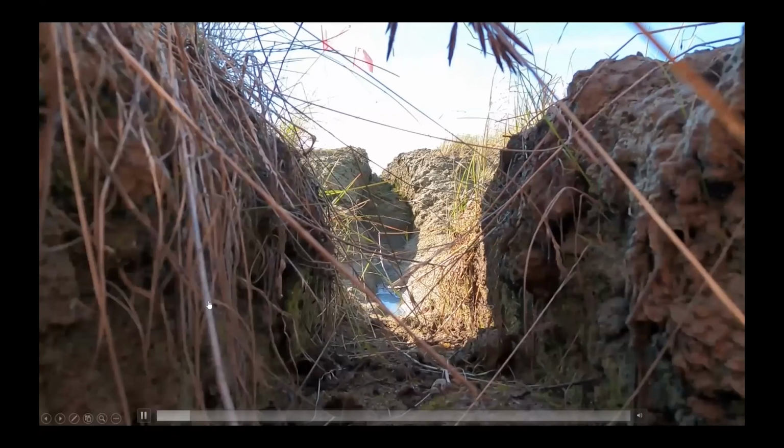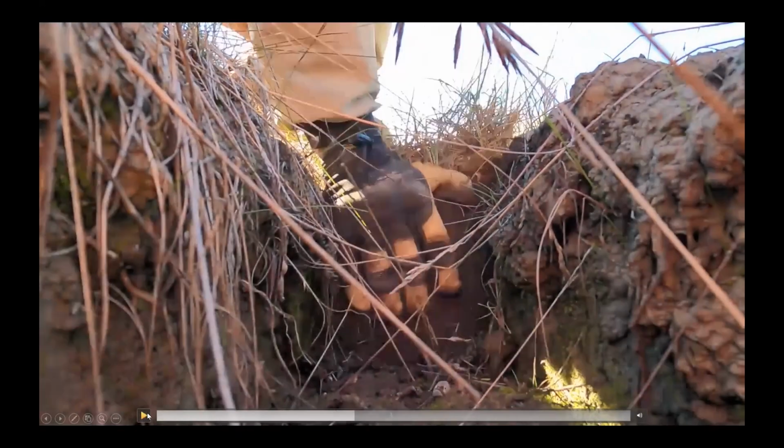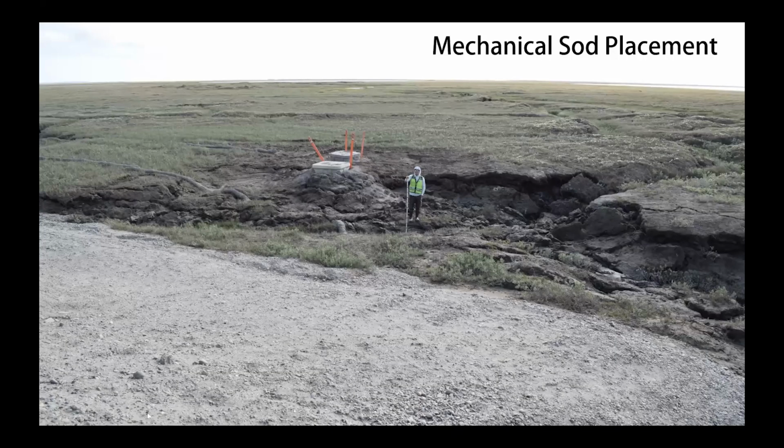Are you dewatering the trenches? In some instances we are, but we actually don't dewater because dewatering is so complicated and the permitting is really tricky. And then when you take the water out, where you put it is really difficult, to find a spot where you're not going to damage tundra by squirting water out. So a lot of times when we're backfilling, so this is the location just south of Dead Horse, a giant hole.